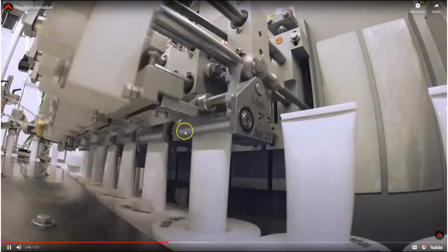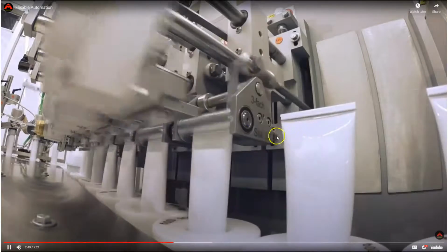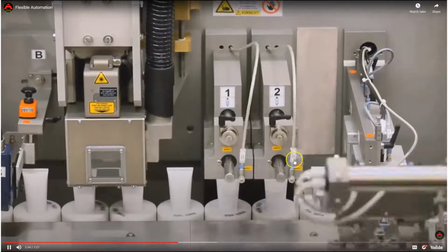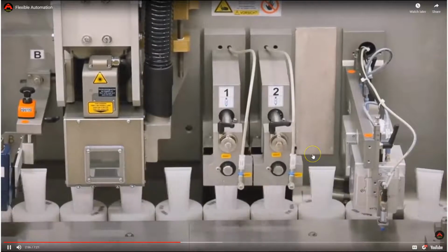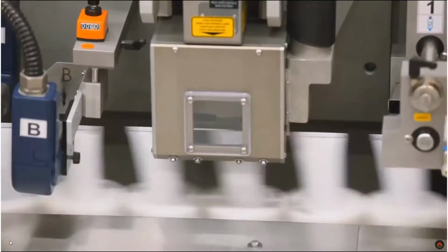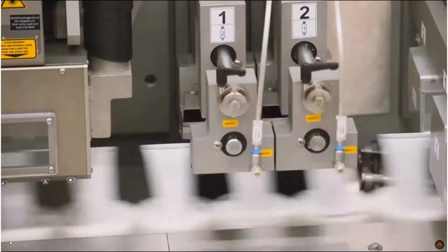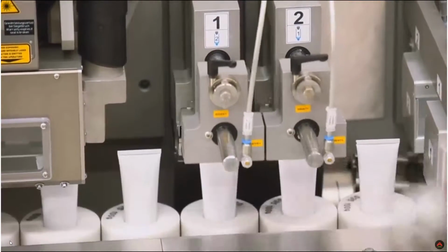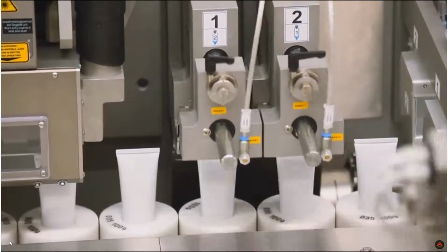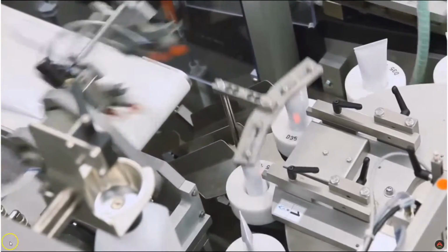And here's the crimping station for crimping the end of the tube, and you can see it's folding it over, kind of like the end of a toothpaste container. Again, an example of fixed automation. Okay. All right, so I think we'll leave this here. All right, so that was just to give you an idea of what fixed, flexible, and soft automation looks like. They're usually an assembly line or a production line is going to have a mix of all that together. Okay, so let's move on.